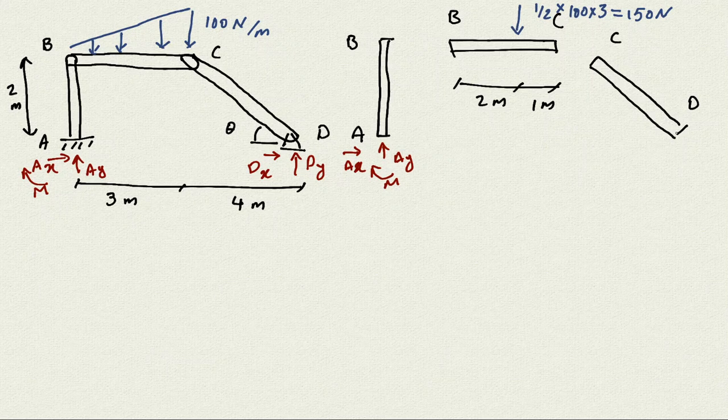Here, because it's a two-member force, whatever is the reaction is going to be along that force. So instead of having the dx and dy, we are just going to replace it with a single force, because it's a two-member, it's going to be along that member. I will assume it might be tension, might be compression, we don't know, I just put it like that.